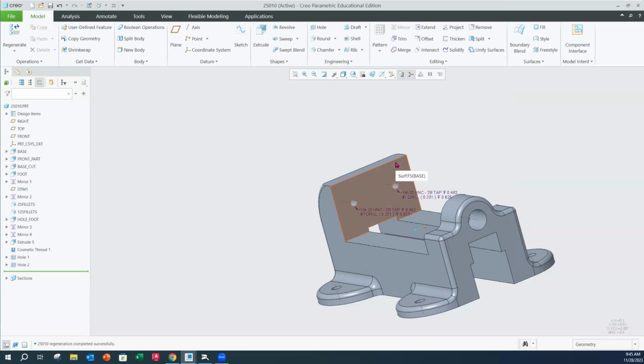We need to show it in that simplified form that we also see for the hidden line of the threaded holes here. You might be saying, why can't we put it in as a regular hole? We could, but there are no options for Acme threads.